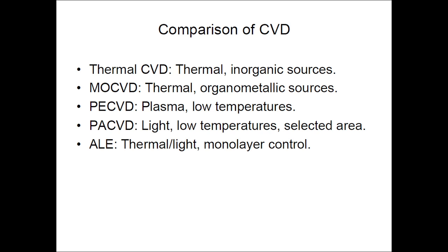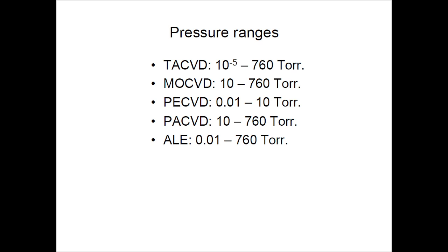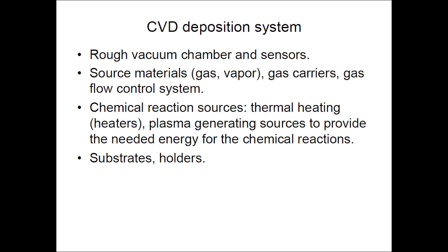In plasma enhanced CVD, plasma at low temperature will be used, and in the photo assisted case, light will be used as a tool to induce the energy, with low temperature and selected area also possible, and the different pressure ranges where you can obtain the deposition, which you can see for the different types of CVD depositions.